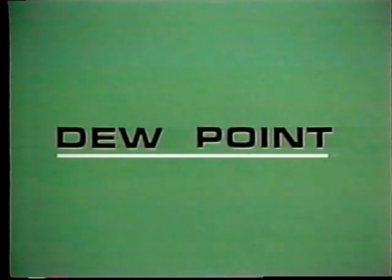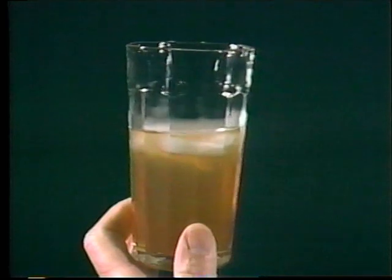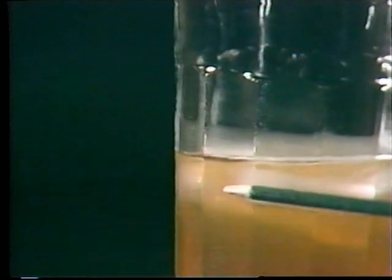To understand why we often need to dry the air after it leaves the aftercooler, we'll need to talk about something called dew point. Dew point is the temperature at which water vapor in the air will condense out. If you've ever looked closely at a glass of iced tea, you may have noticed that water from the surrounding summer air will condense on the glass, up to a certain height on the glass.